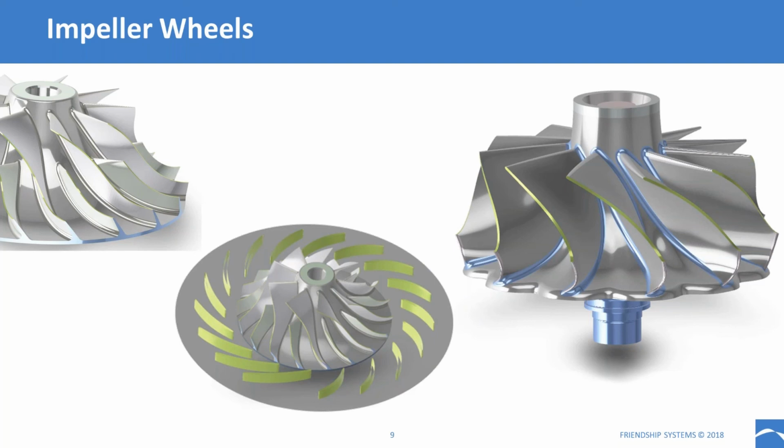So we can model the blades, the meridional contours, as well as a lot of additional details like the filleting that you see here at the root of the blades. This turbine wheel is especially interesting because it also has this webbing, there are different names for that, to reduce the inertia, as well as some contouring on the hub, so some end wall contouring.